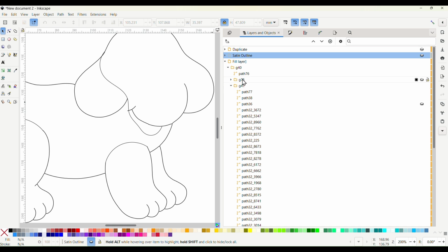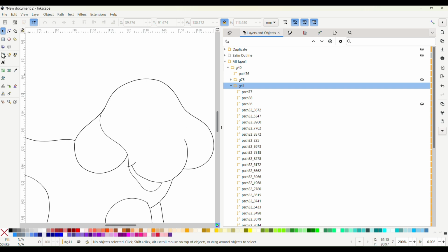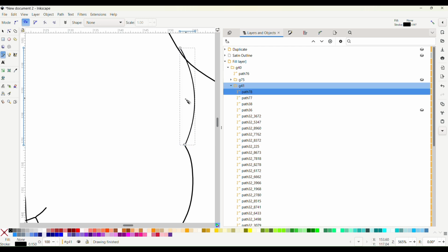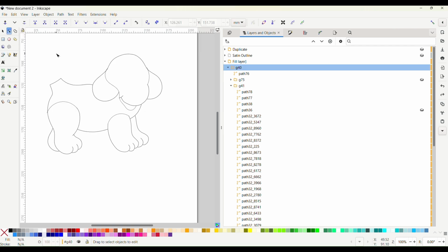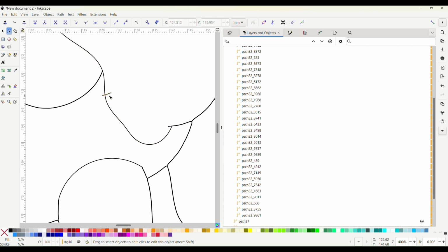Okay. Then go back into my group again, right here with my Bezier tool. Make sure we're overlapping. Hold my shift key outside, hold my shift key down again, and that should work. So we are going to break it apart there. We're going to delete this segment there. Delete that.